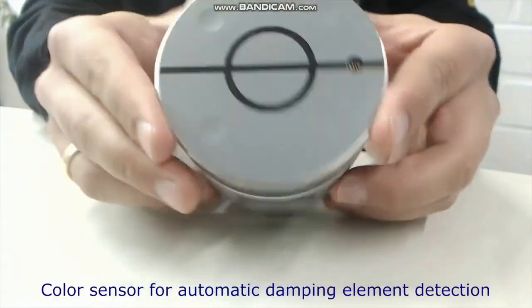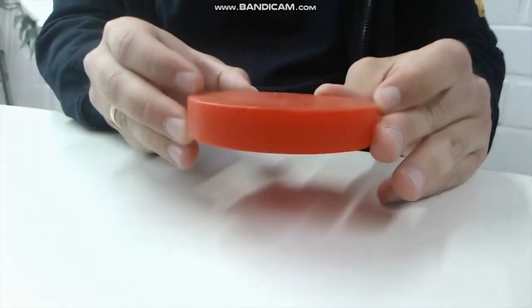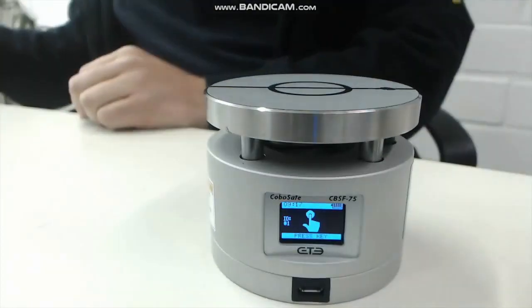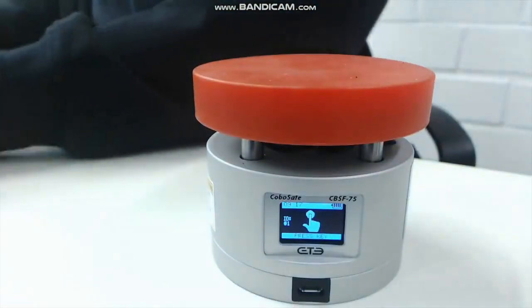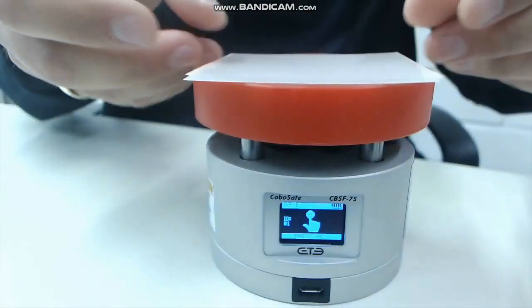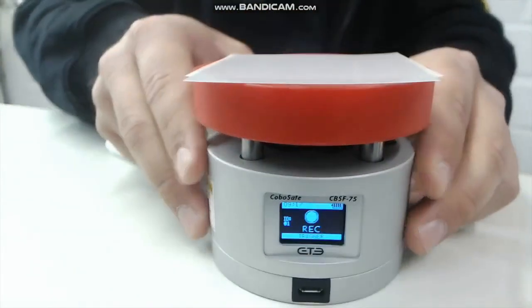For measuring force and pressure, we need the spring constant with a built-in color sensor, the damping element, and the Fuji Prescale measurement films. Start the process with selecting the right combination of spring constant and damping element, apply the damping element, put the measurement films on top, and make sure that the rough sides lie on top of each other. Finally, the microfiber cloth is applied.